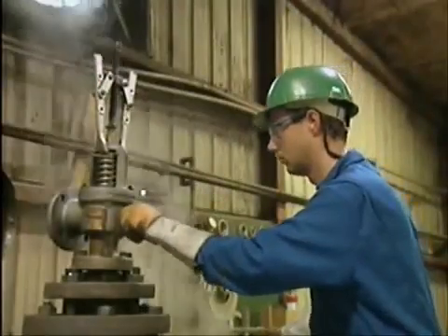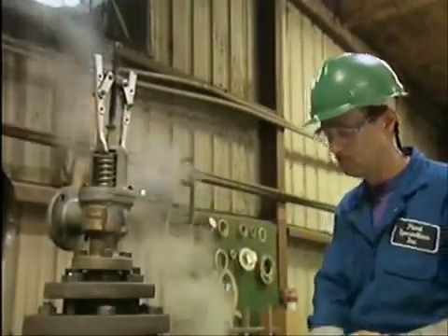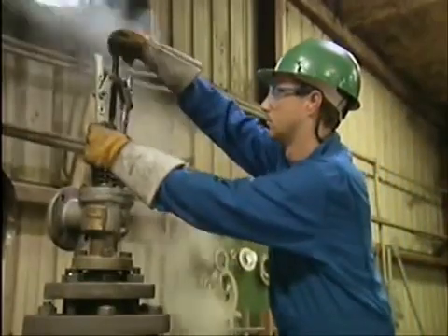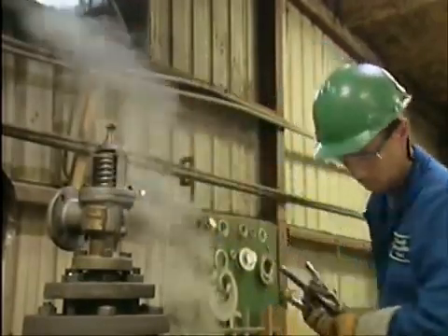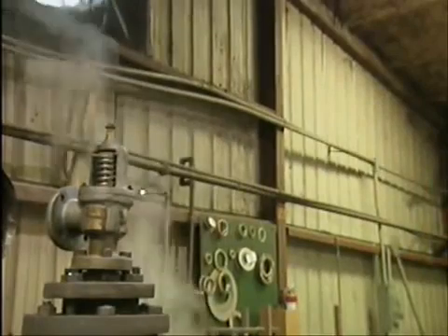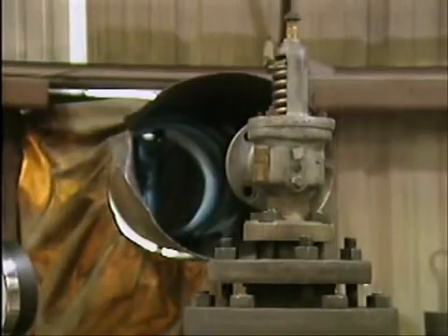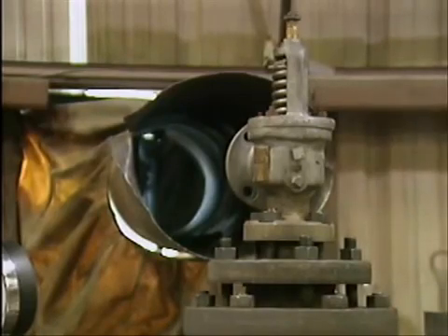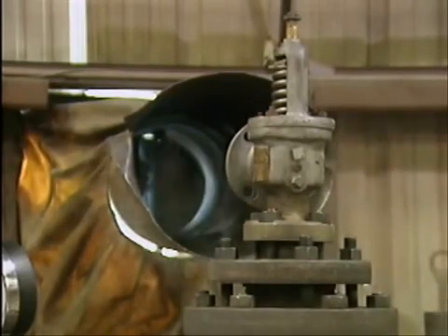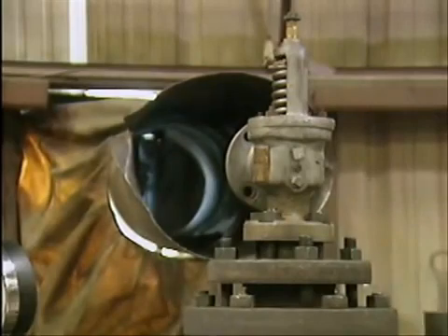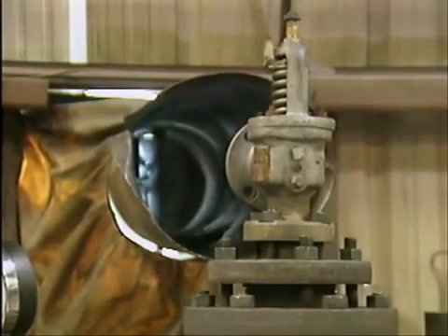After you complete a hydrostatic test, you should remove the gag when system pressure has been reduced to 85 to 90% of the valve's set pressure. Never leave a gag on a valve during normal system operation, because a gag makes a valve inoperative and leaves the system or equipment that the valve's installed on without the necessary protection from excess pressure buildups.